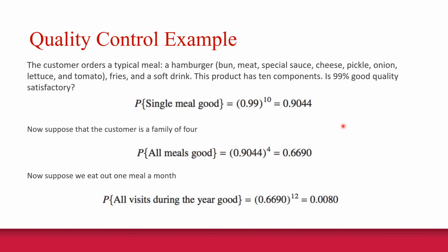This shows you exactly the power of statistics and why it's important to achieve plus or minus 6 sigma. Because with plus or minus 6 sigma, these numbers look a lot better. Again, you're never going to get 100%, but manufacturing to plus or minus 6 sigma, with that reduced variability, gives you much better odds of the product being good, especially if it has multiple components to it.